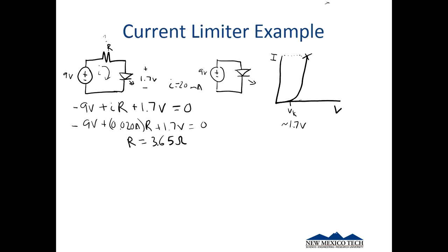If you look at your kit, you'll notice that I don't think I have a single resistor that's less than 365 ohms for you. I don't remember what the lowest one in there is. It may be 470. But I chose my resistor values so that we could do this. So that's a current limiter, and it'll just depend how you've got your circuit set up. The general idea is you want to be able to limit I by choosing an appropriate R.